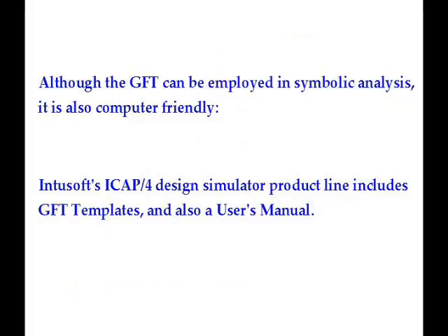Although the GFT can be employed in symbolic analysis, it is also computer-friendly. Intersoft's ICAP4 design simulator product line includes GFT templates and also a user's manual. The GFT template quickly makes available Bode plots of all the simulated and post-processed transfer functions. A reduced template produces the loop gain only and reads out the phase and gain margins.